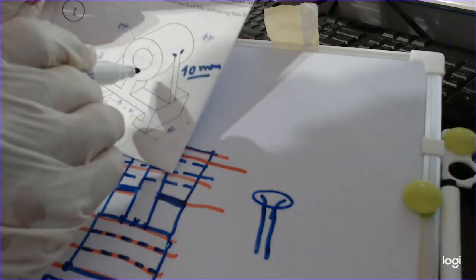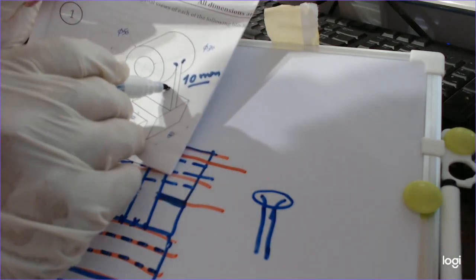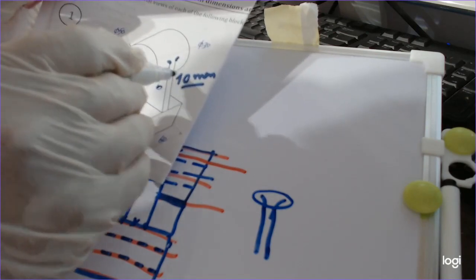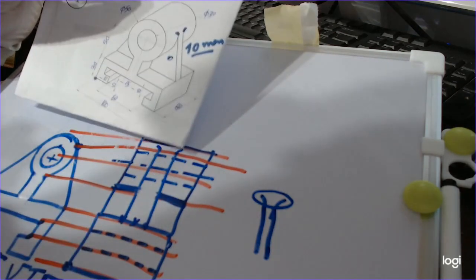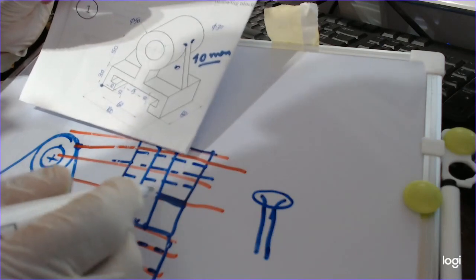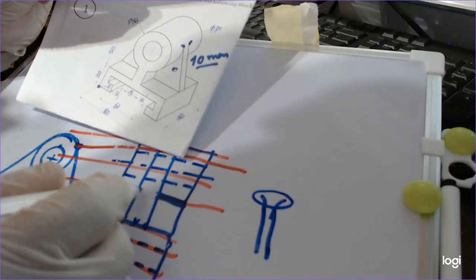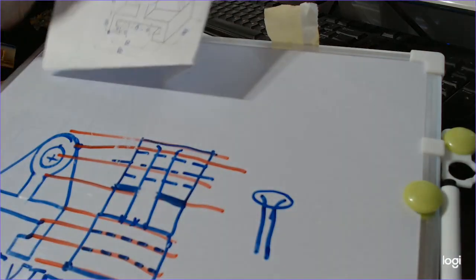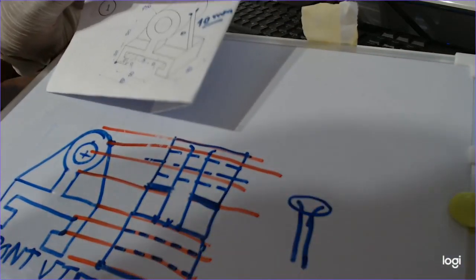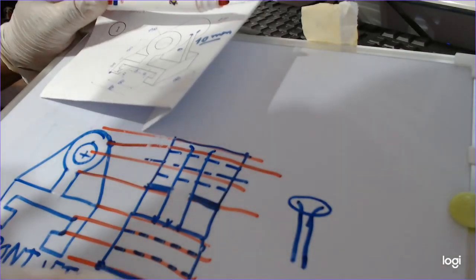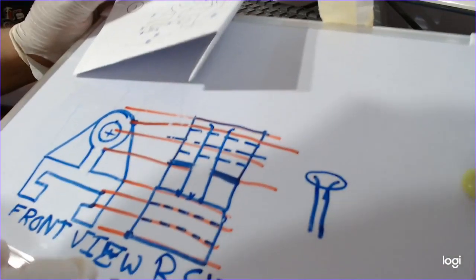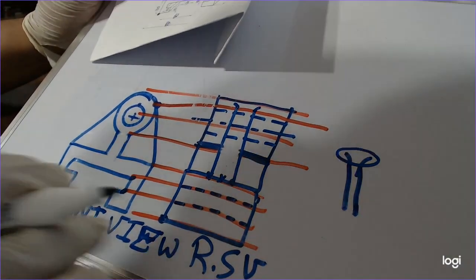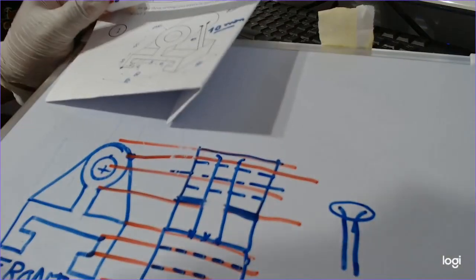And actually the cylinder will stop at this face of the web and then start with the back side of this web. That means that we don't have any lines here, and actually we don't draw dash lines here. Okay, so now we end the side view, the right side view of this object.